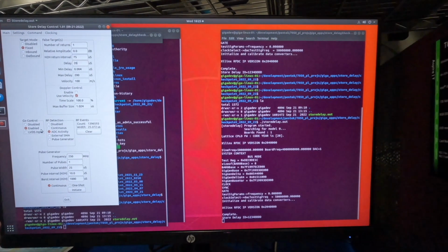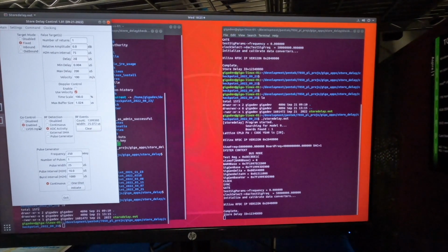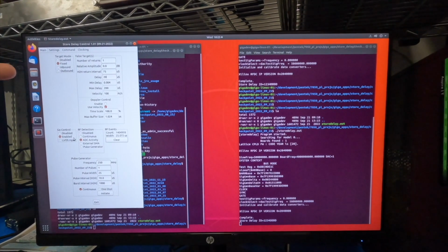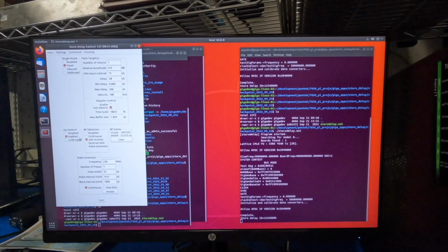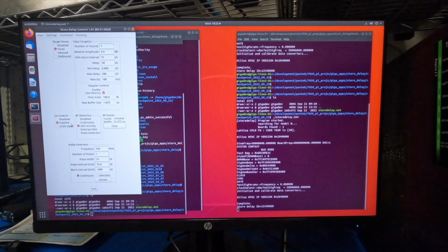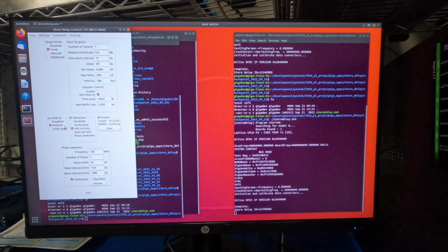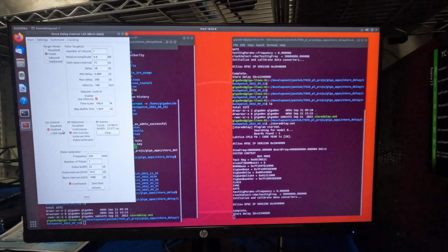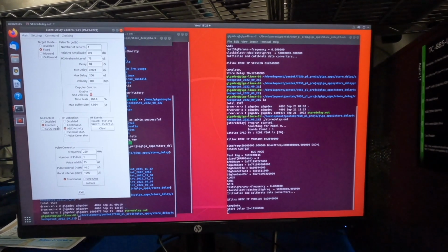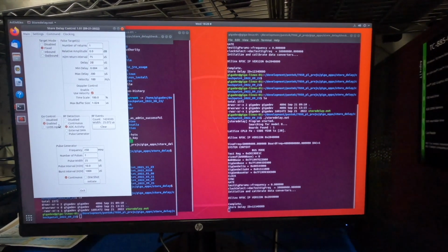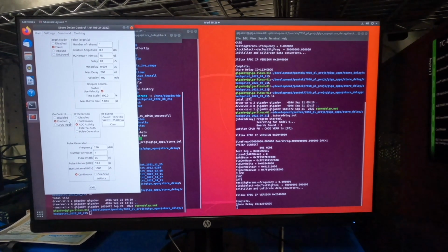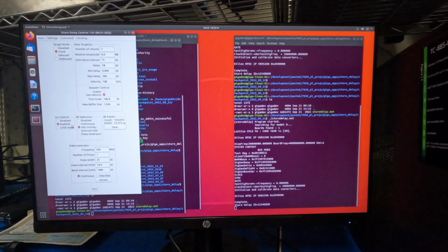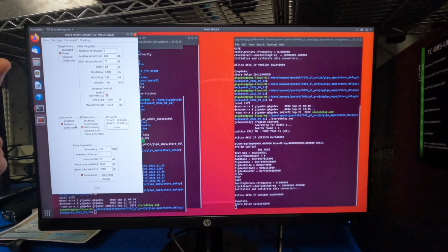And then what we're going to be doing is changing the output of the DRFM target mode for both fixed repeats and also inbound and outbound repeats, because we're going to be doing moving target returns from the one signal it does get in. And for the false targets in this particular setup, we can change the number of returns, the amplitude relative to the input, which is very important, especially when you're doing cover pulse type things, the head-to-head interval between the rising edge of the pulse on the first return and all the other subsequent returns, and the delay from when it sees energy to when it puts out energy.